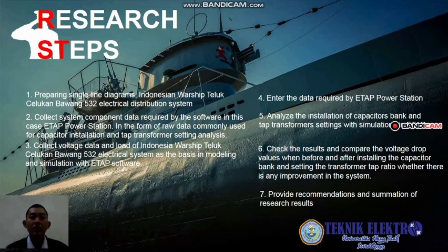Fourth, enter the data required by ETAP power station. Fifth, analyze the installation of the capacitor bank and tap transformer setting with simulation in ETAP. Sixth, check the result and compare the drop voltage values before and after installing the capacitor bank and setting the tap transformer ratio, to see whether there is any improvement in the system. Last, provide recommendations and a summation of research results.